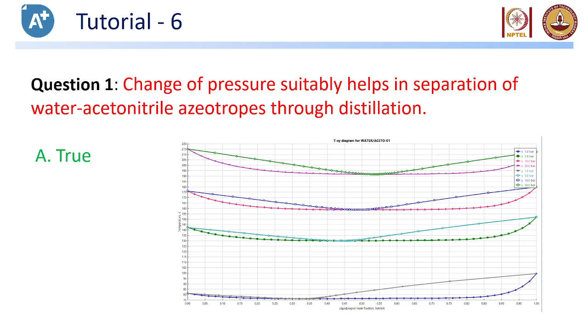Yes, yes. We can't get stuck. In normal distillation where we don't have azeotrope, two components can be separated using one column. However, if we have azeotrope, we won't be able to separate them that way. We need two columns for two components because we have azeotrope at the other end. If you want to do the separation using the pressure approach, you need two columns. Correct.